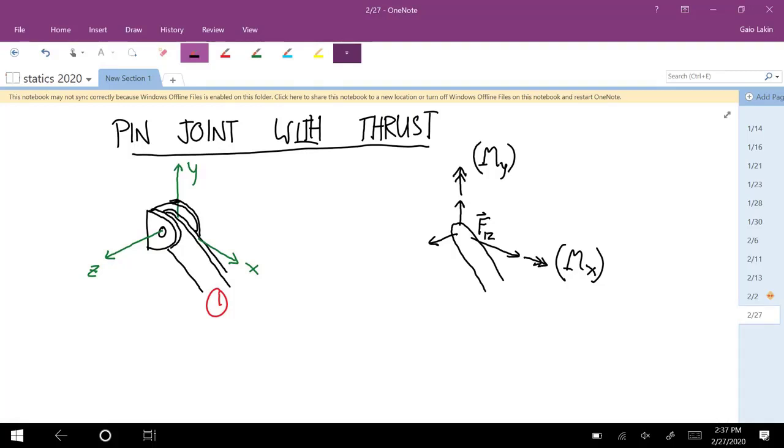They are only there if there's not a second pin joint along the same axis. Okay. And again, like in the first case, they'll apply those couples, but you don't want your kids hanging on it. Yes? Can you draw that just with your double arrow, single arrow, or did you have to draw like? Say it again. Can you just, instead of having a force arrow, can you just draw a double arrow going up? No, because those are only couples. The double arrows mean a couple. So you have to also show that there's a force.